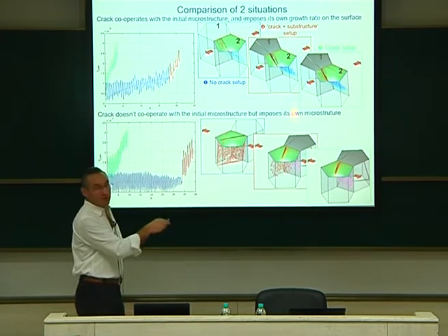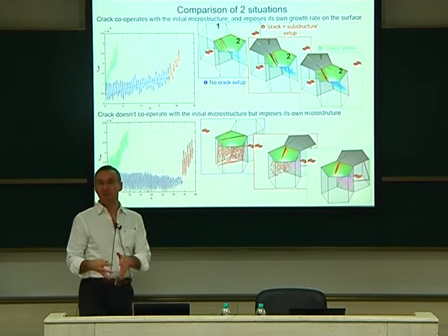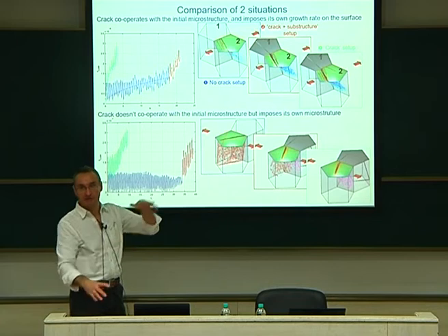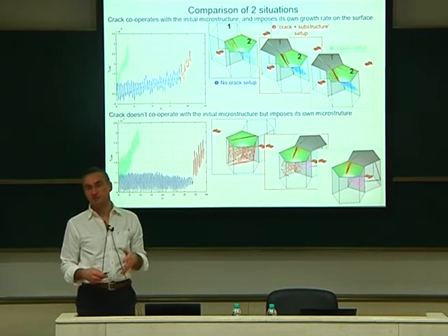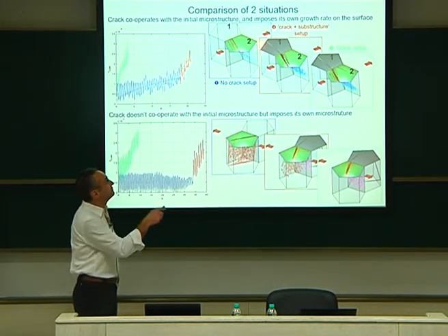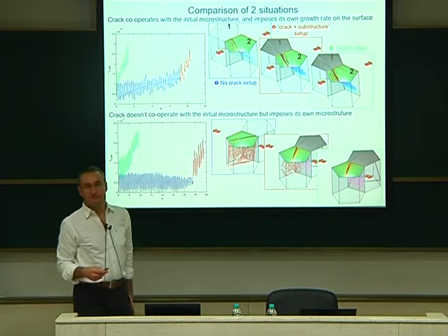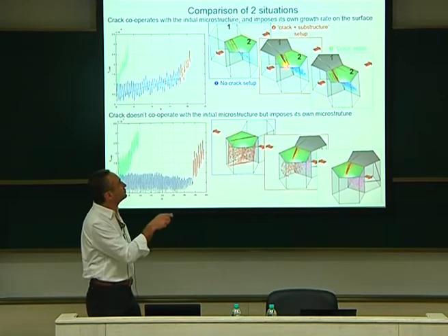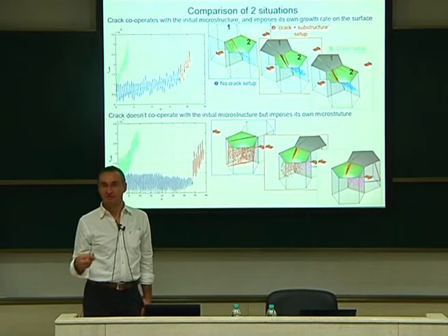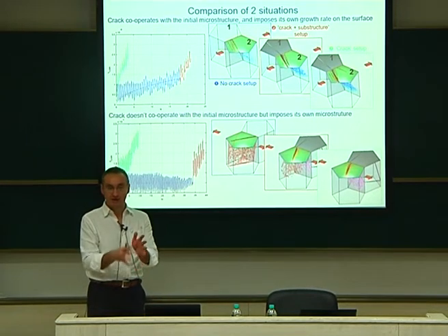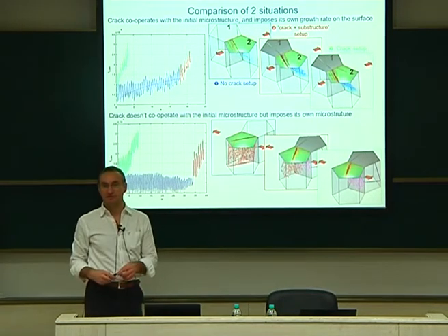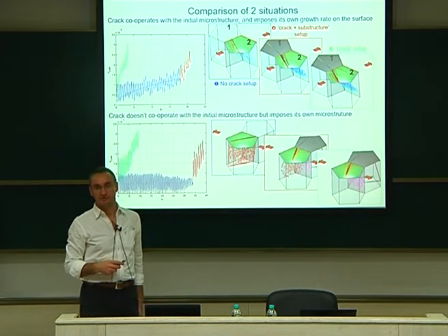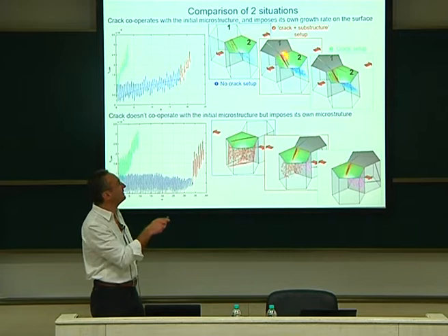But again, this is not meshed by FEM. This is just an analytical expression of a 2D crack tip, as if it was an infinite, planar crack. This could be modified. Today we are working on that with XFEM, a generalized finite element method, in order to let the crack appear where it wants. I think that will be nice. You do your crack and let it move as it wants in FEM. But this requires a very fine mesh locally, so it's quite complicated, and we are working on that now.